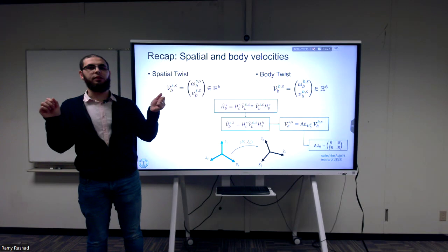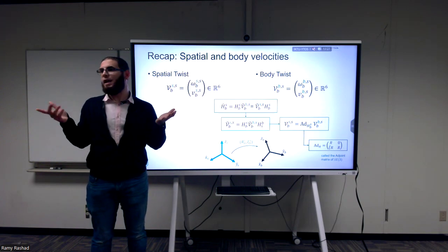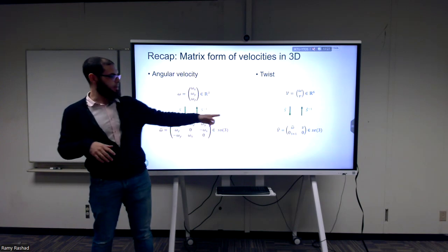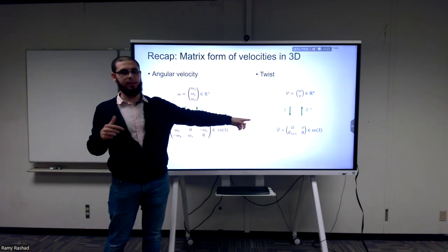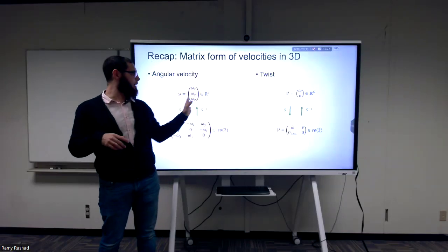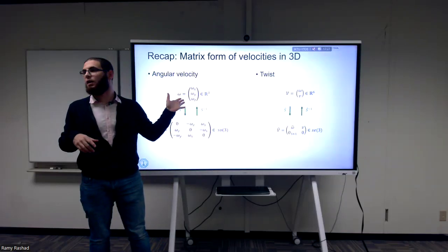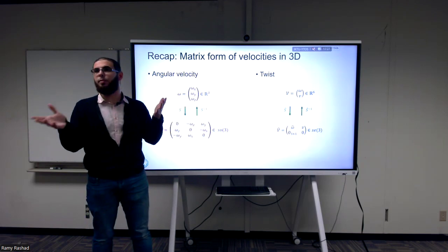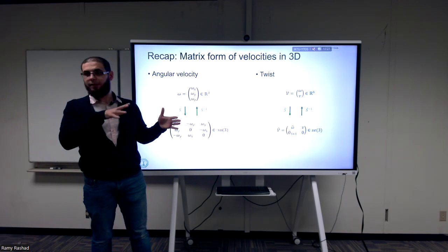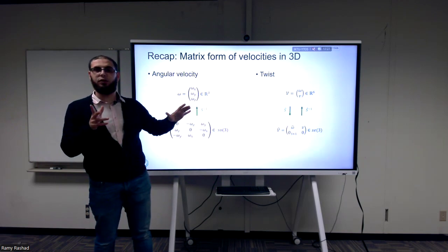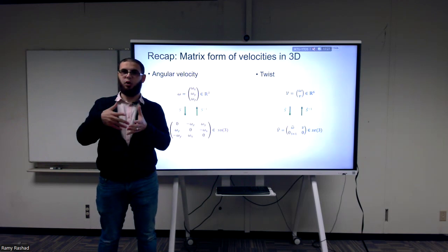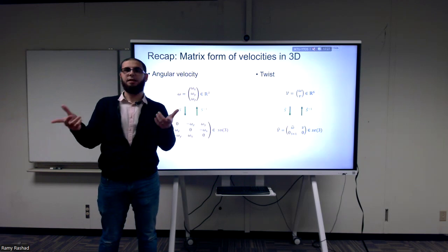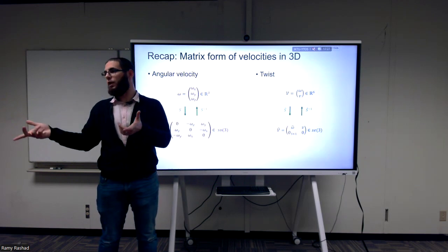We're going to be differentiating between 2 kinds of twists because they are the most natural ones. We said that the twist, if we go back, so this is the angular velocity in tilde form, and this is, sorry, the twist in tilde form. We removed the indices because we can represent this angular velocity in any frame you choose. Any frame that you have in your setting, you can represent angular velocities or twists in that frame. If we're talking about the twist, which is the relative generalized velocity between frame B and frame S, then it sounds natural to represent the twist either in frame B or frame S.